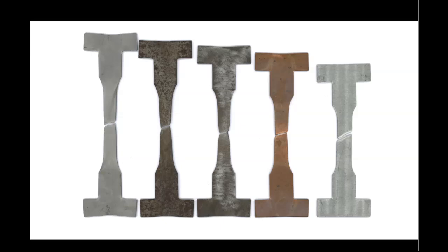Okay, you need to take the dimensional change and relate it to the mechanical behavior of the material. So if you can contrast it well, that's great. Secondly, what is important is that you see if a material, so we're pulling materials apart in tension. As we're pulling it, we initially tension the material and it's elastically deformed, then it starts to plastically deform, and then it deforms up to the necking point, and then we start to descend into the fracture.